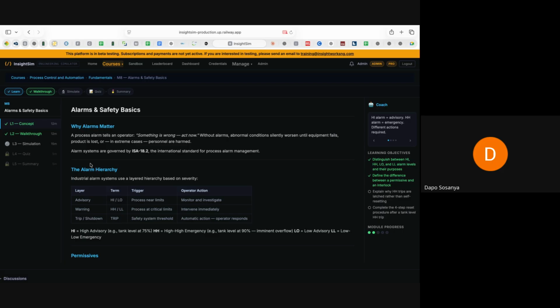That's what the alarm does. A process alarm tells an operator something is wrong, act now. Without alarms, abnormal conditions silently worsen until equipment fails, product is lost, or in extreme cases, personnel are harmed.